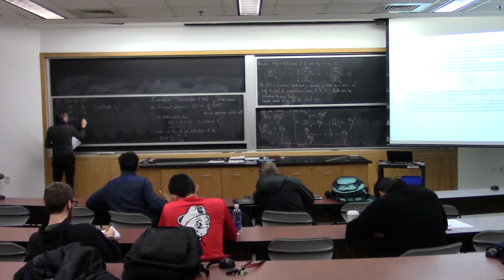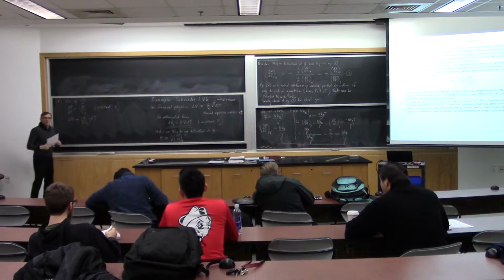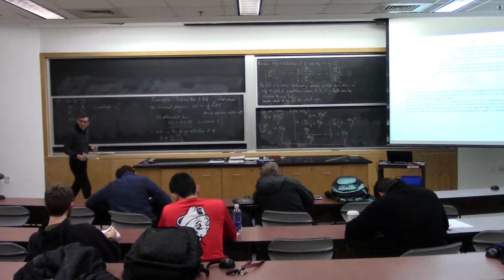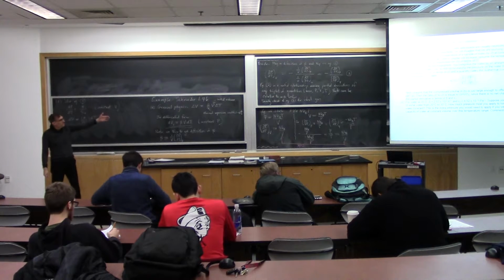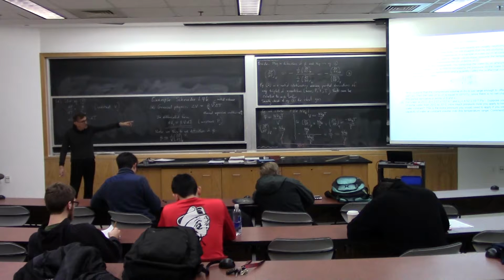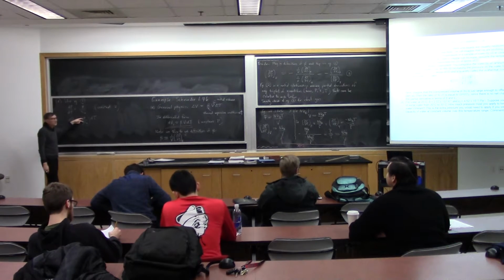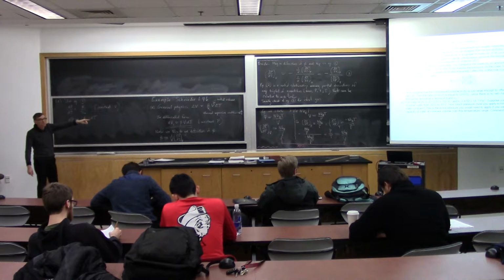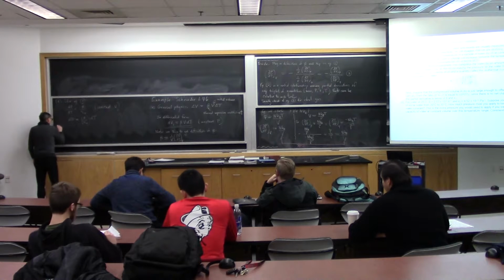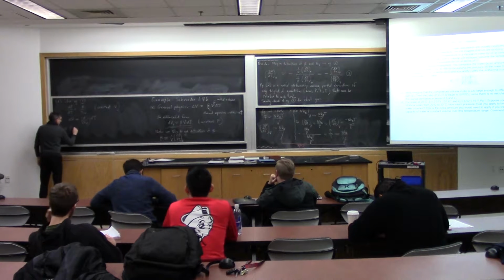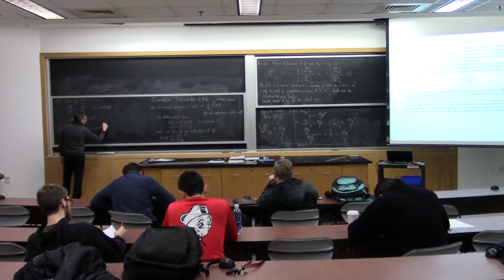That's the thermal expansion coefficient over the isothermal compressibility times the temperature change, dT. We can assume, since we're just given constant numerical values of beta and kappa T, that these quantities do not change over this temperature range for the water. So we treat beta and kappa T as constant.